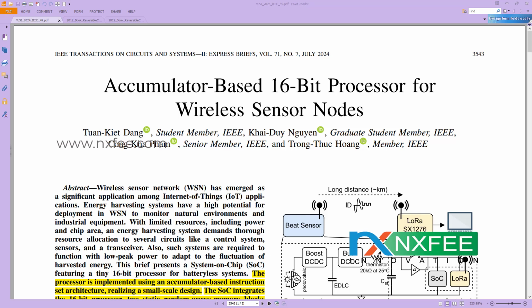FPGA. The architecture performance is verified through extensive simulations in ModelSim, and a comparative analysis is conducted to evaluate the key parameters such as area utilization, processing delay and power efficiency. The result demonstrates that the optimized dual accumulator based RISC architecture significantly outperforms the traditional single accumulator design, making it an ideal solution for modern embedded applications that require both high performance and low power consumption.